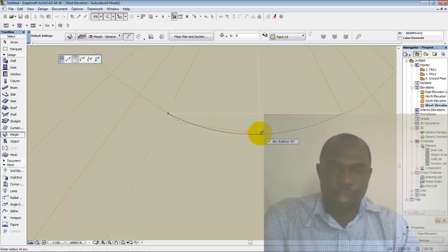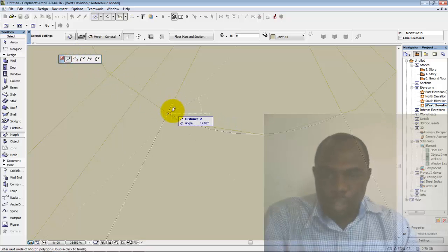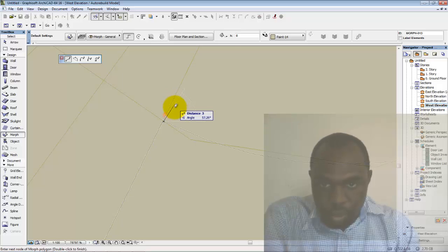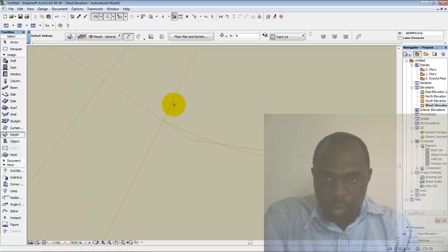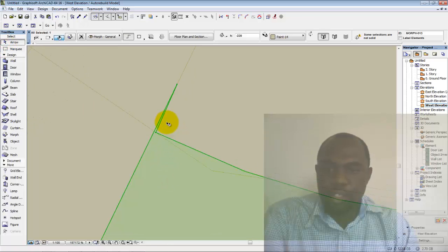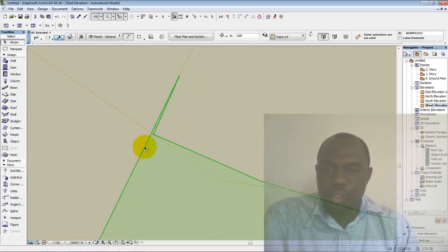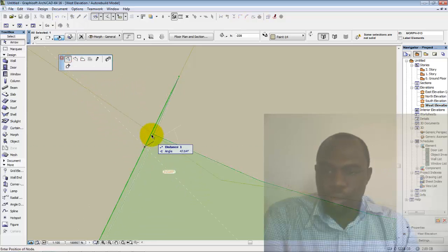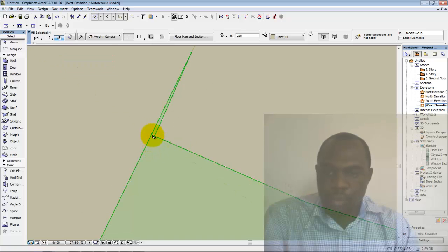Draw it around here. So go to the straight line tool, select the edge where we started, where we made our mistake. So after drawing that, we need to rectify this shape. So to do that, we select somewhere on this line to introduce a node here. That's like an anchor point. Select if that's the node, that's it here.